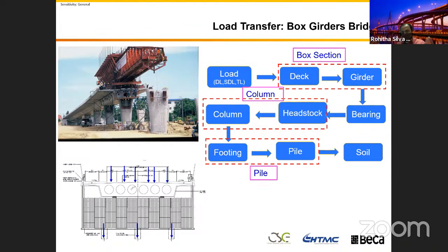We changed the whole bridge design. We replaced it with permanent planks, and then we designed the bridge. When you use this kind of bridge, you don't have that problem, because for this segmental box girder bridge, we prefabricate these elements in the yard. We bring them together like a jigsaw, assemble them, and post-tension on site.